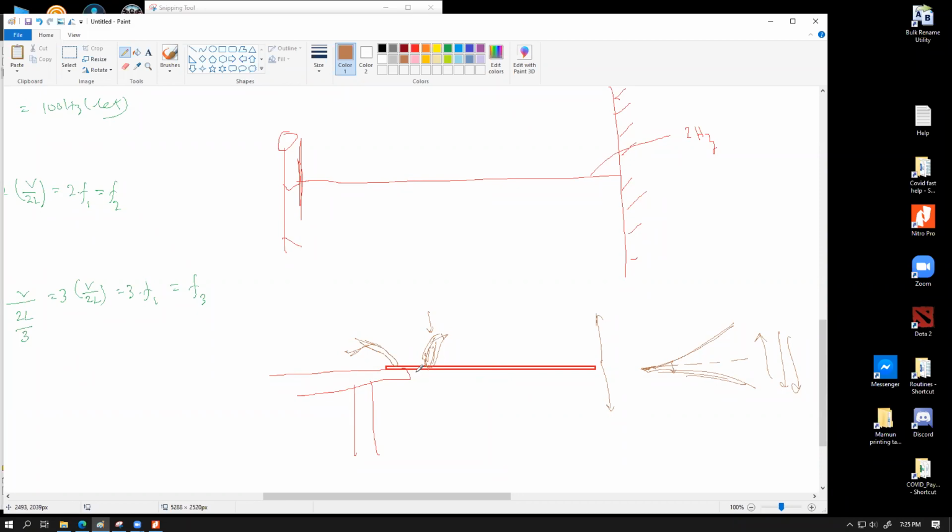Once the ruler is going down, we apply force for half that motion. Then for the next half, as the ruler is coming upwards, we are not applying force. So we match our hand's applied force frequency with the natural frequency of the ruler for this length, and we can make the ruler go at a pretty high amplitude. It is not necessary that our hand be exactly at the end. We can place our finger pretty close to the table and apply a little force. It all comes down to how much energy we are adding in every movement.